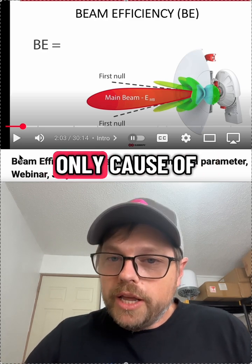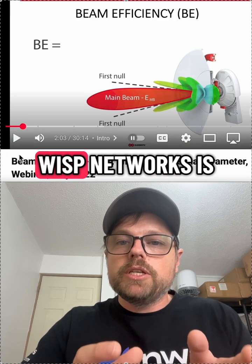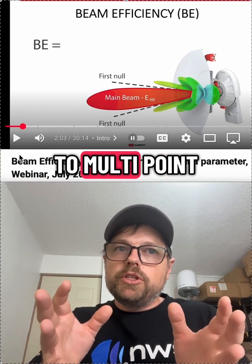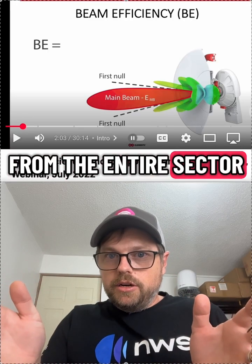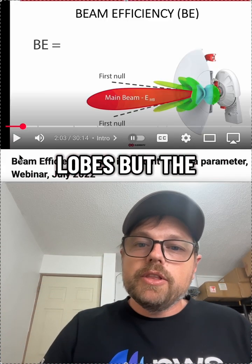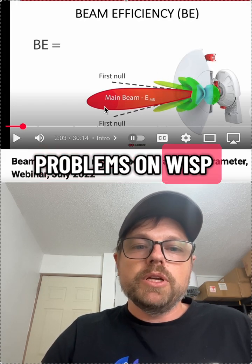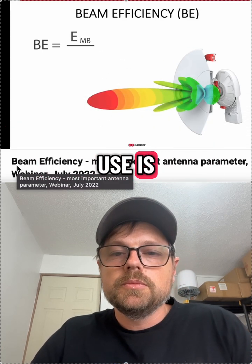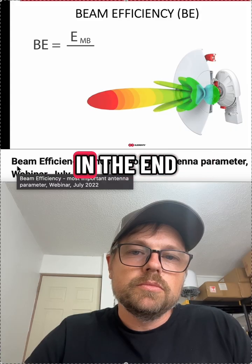They're not the only cause of noise within WISP networks. Again, a lot of the noise in WISP networks is picked up within that main beam, particularly with point-to-multipoint sector applications. You're going to be picking up noise from the entire sector. And you could be picking up noise from the side lobes, but the side lobes are not the only cause of noise problems on WISP networks. The higher the beam efficiency of the antenna you use is, the better for your network and the end users of your services in the end.